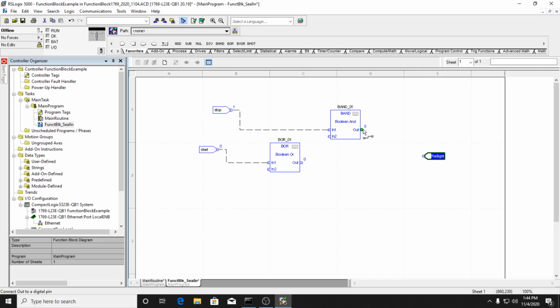All right, and so I'm going to connect this output. So I click on there, you come over there, you see the green dot, I connect those, those are attached. And then I'm going to take the output of this OR and feed it into the input of my AND. And then I'm going to also click on here and feed back here. This is my seal-in circuit, and what's sealing it in is this feedback line right here. That's what's sealing that in.